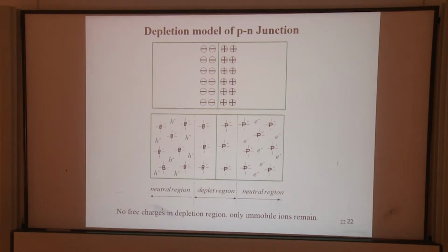If you think it's on the right-hand side, please raise your hand. Okay. Oh, still someone. Okay, let me think about that. I'm talking about N-type. So for N-type, we want to create electrons, right? So we dope the element that has more valence electrons than silicon. So we need to dope a group 5 element in the group 4 silicon crystal structure. So we need to dope phosphorus for N-type. So the right-hand side is N-type, nothing on the left-hand side.